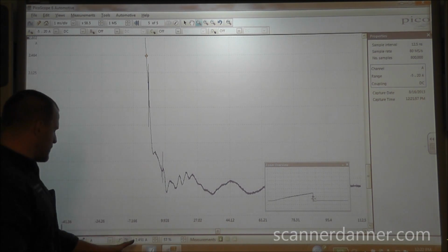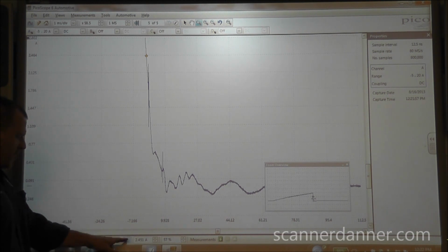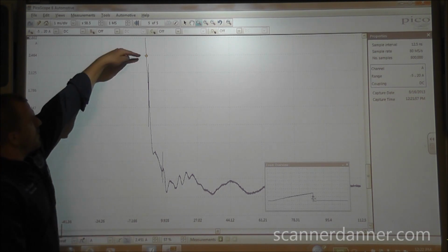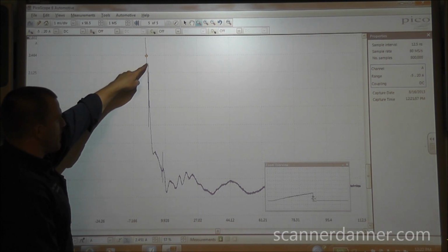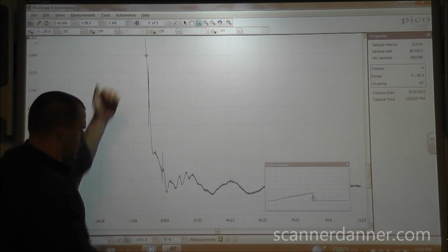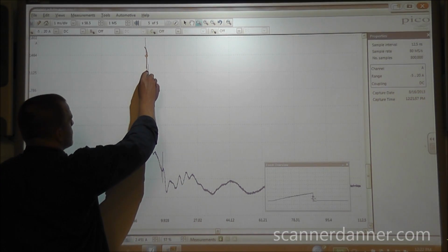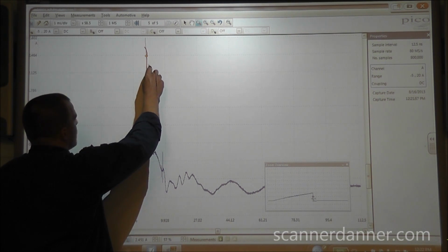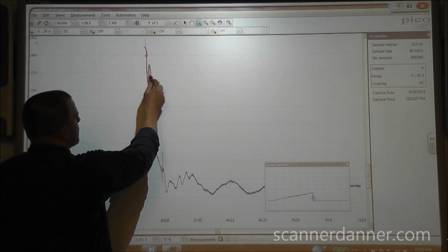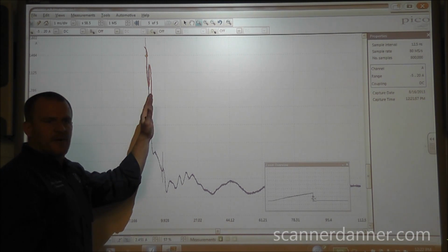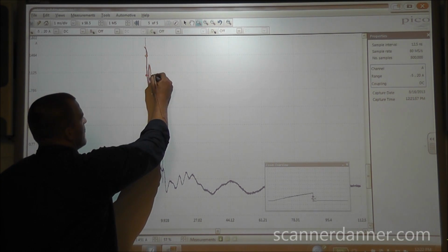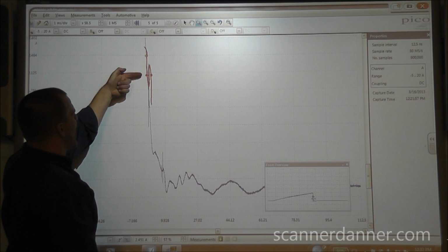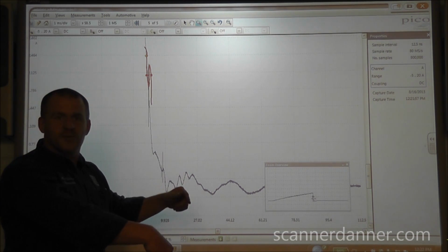When we're triggering, right now what we're telling our scope is to trigger in a falling direction. I have my falling one showing here at 2.4 amps. Right here is my trigger. If I set it right here, do you notice there's another spike in here? As this signal is falling, there is a spike here, and then it falls again. So will this give me a little bit of a wobble, possibly in the pattern, if I set it there? Will it sometimes draw in this location and sometimes draw in this location because both of those are at the same trigger level in a falling direction?